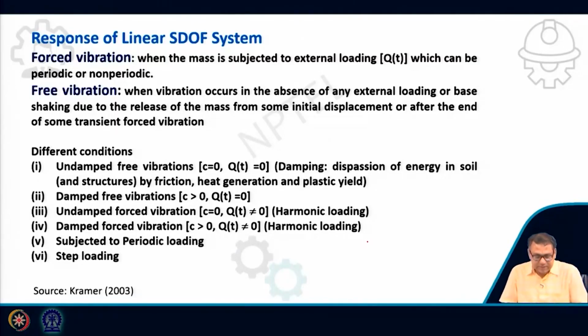So this is my equation: M u double dot plus C u dot plus K u equals Q(t). Here Q(t) is equal to 0 because it is free vibration, and C is equal to 0 for the undamped condition. That is one condition.